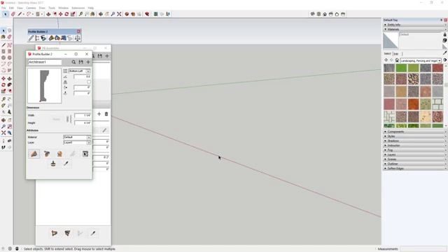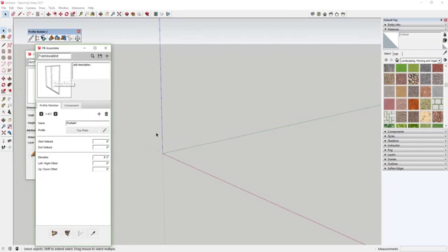When you do this in a wall assembly, your top and bottom plate, the framing that lays sideways that the other boards sit on top of, that's going to be a profile. And then the other piece is the stuff that gets copied along that length. In this case, that would be the studs that run up and down, if that makes sense. Let's go ahead and walk through it and I'll show you what I'm talking about.